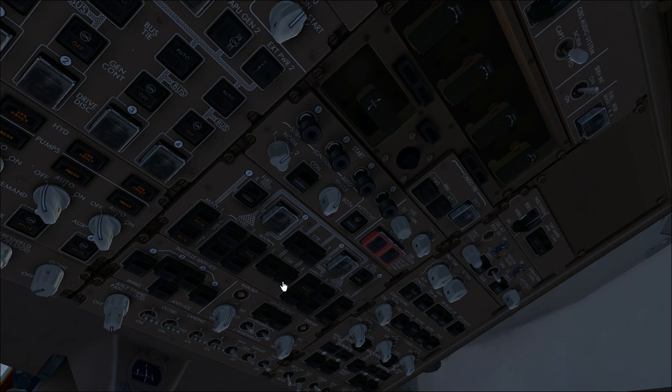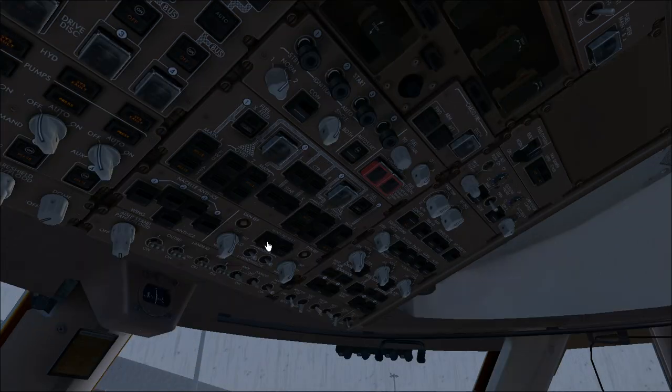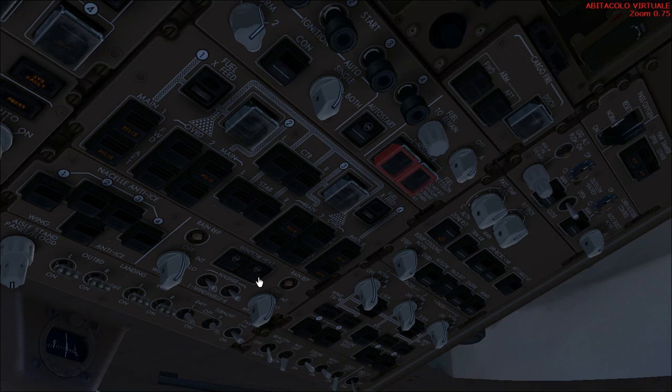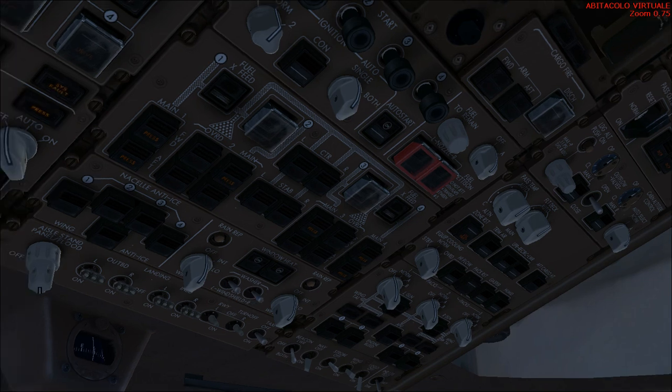NTIS panel is set, nacelle anti-ice switches are all off, wing anti-ice switch is off, and the valve lights for both of them are extinguished, that's fine. We have the windshield protection panel here, we have to set up. Windshield you can set on and check the inoperative light is out, and the windshield wiper selector must be in off position, they are in off position. We now can move to the lighting panel on this side and check landing light switches, runway turnoff light switches and taxi light switches, all in off position, and this is cross checked.